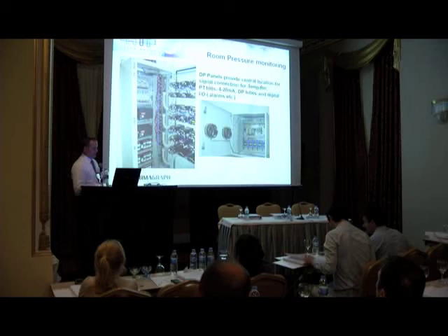These little alarm indicators, go back a slide, these little alarm indicators here have a number of colours. Red tells you you've got a critical alarm, the yellow tells you you've got a warning, and you might want to take some action before it becomes a critical alarm. Green is healthy, cyan is for when there's a particle counter on there and the device is turned off, and this magenta or purple colour unfortunately tells you you've got a faulty sensor.